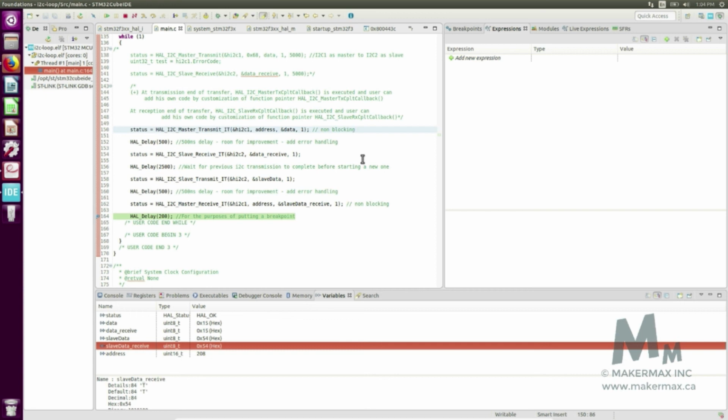On the hardware side, you need to remember that I2C operates over open drain, and open drain means that when none of the I2C devices are activating a bus line, which is either the SDA or SCL, the line is floating. So it's your job to pull it high when it's not being used. That's why on the master, I2C1, we used the internal pull-ups to pull it high. And the job of the master or the slave would be to pull it low whenever it wants to send or receive data. So that's how open drain works.